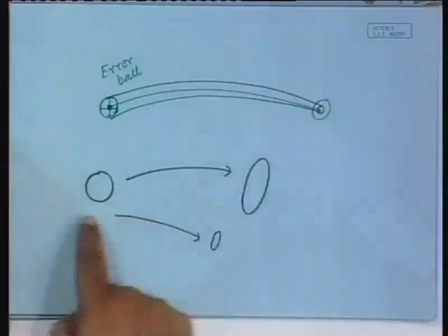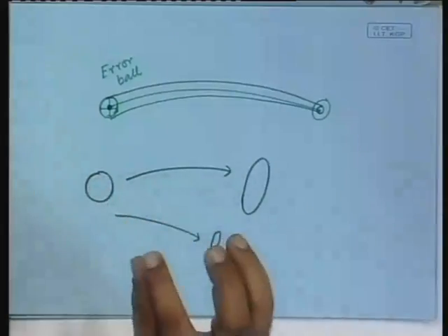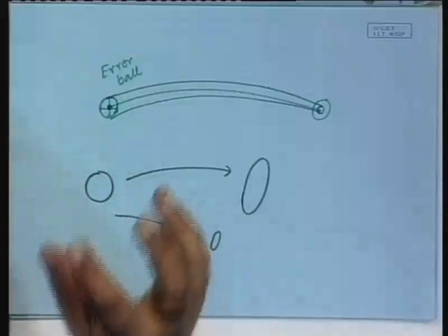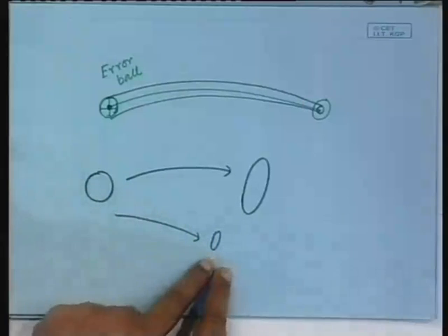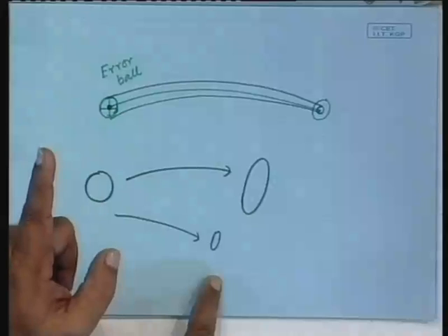So, these are the two types of systems that we had encountered so far. The systems that we see around us, which are stable, have this property that in all the directions they shrink, and if they are unstable, they expand and expand and go to infinity. We learned how to keep instability within bounds, how to stabilize the system. That is the whole gamut of control theory. Just one concept: if you start with a set of initial conditions as the error ball, a circle, then it will take the shape of an ellipse if the eigenvalues are real.